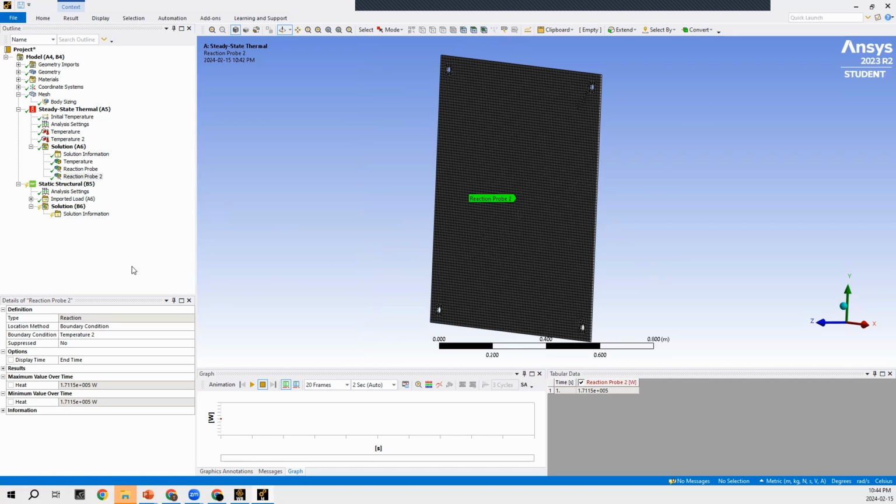And this is where the holes that I created in the panel come into play. I'm going to go ahead and add a fixed support for the bolted connections, acting as if it was bolted to the structure of the cabinet. Therefore, the panel would be restrained at the four corners, but be able to warp in any direction that it needed in reaction to the thermal loading on it.